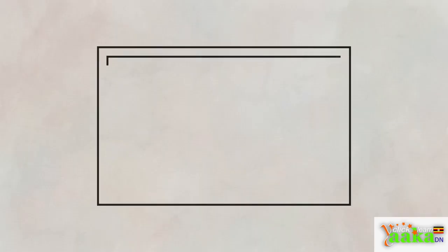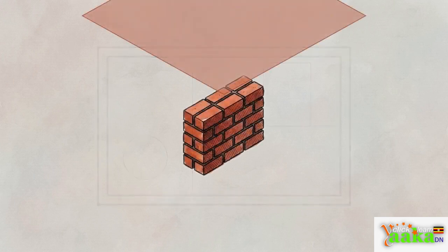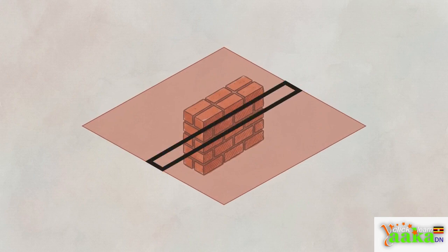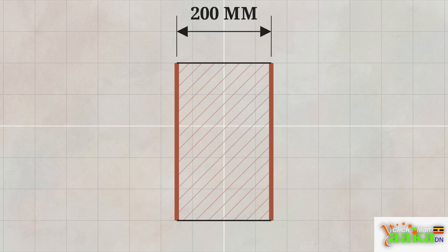Look closely at this floor plan layout. Notice how the external wall lines pulse with a heavy, thick line weight. Thick lines are strictly reserved for materials that have been actively cut by your horizontal or vertical section plane. For exam purposes, standard brickwork external walls are typically drawn to represent exactly 200 millimeters in thickness.